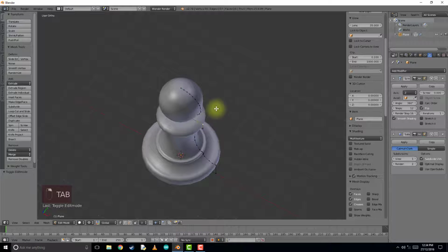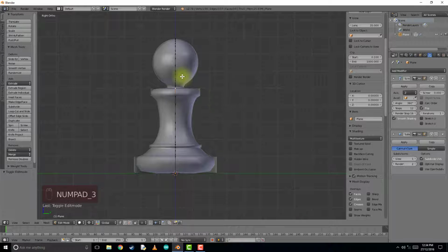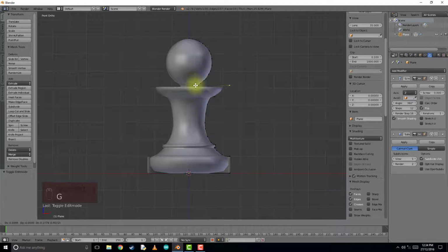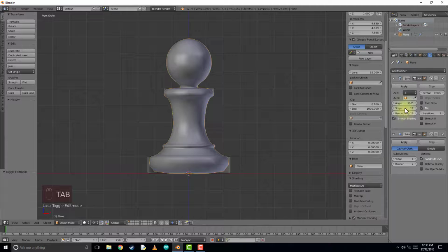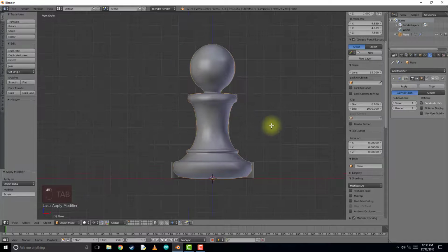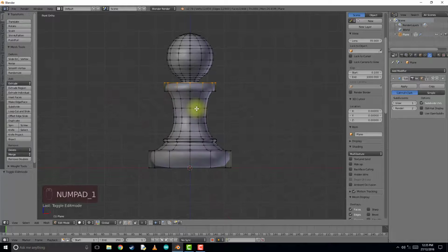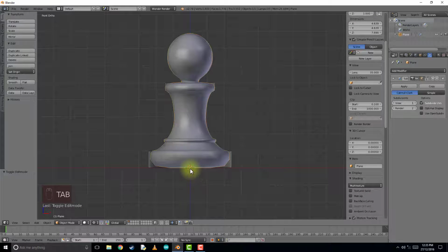As you can see, when we're editing this, we're still only editing the outline. This is because we have not applied our screw modifier. So we'll apply it now. And now when we edit it, we're editing the object after it's been screwed around its location. And the location it screws is the object center point, which we had automatically set. That's the standard.